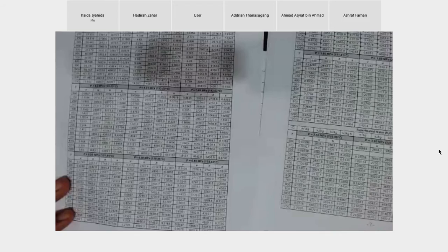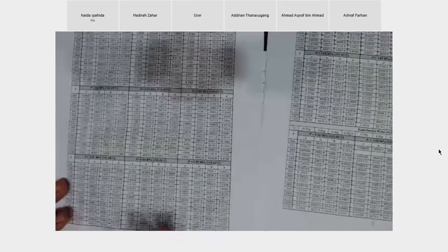And later on, when we identify that the system is superheated vapor for the water, then from there we use table C. Okay, so table C ni, the C1, C2, C3, C4 ni, is only for the case of superheated steam. Okay, otherwise we only use table A1, A2 or B1, B2. Okay.